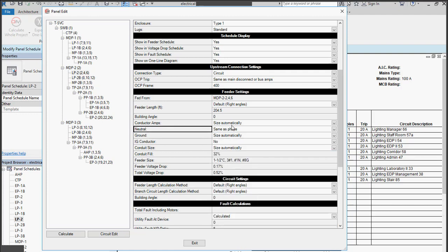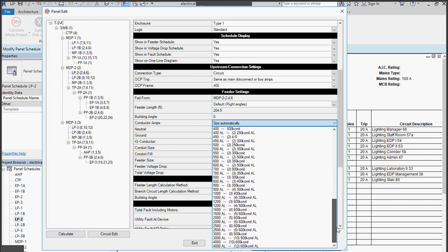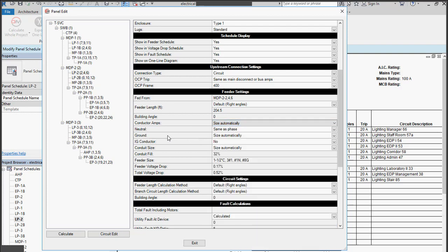For the conductor wires, that's actually controlled based upon the wire ampacities, which we'll look at in just a moment. So that new E wire that we created, we actually can't use anywhere because it hasn't been set up as a wire ampacity. Because neutral and ground, we're not doing a whole lot of sizing based on that, so we don't need to know a whole lot more information about it. For the conductors, we need the impedance values, and so you have to set that up a little bit differently to use those.